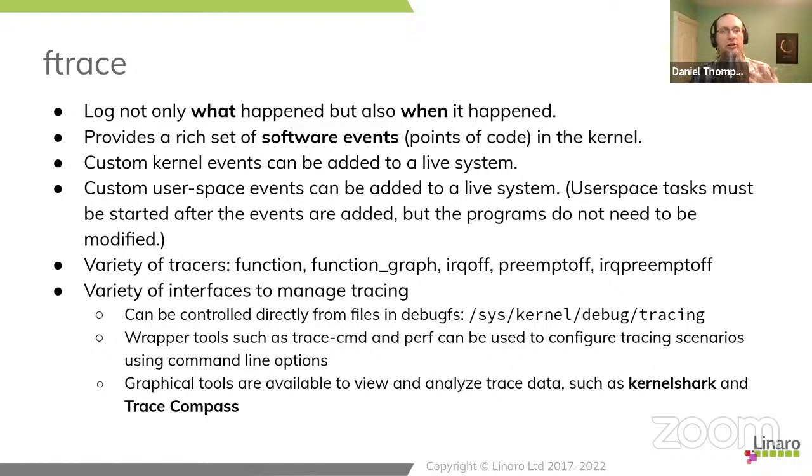And we can look at those events in different manners. So fundamentally, we've got function trace and function graph trace. If you have a real-time system where you miss a deadline, the usual question is, what was the kernel doing instead of meeting my deadline? So this will help you look at the functions, how long they're taking, which threads are running.